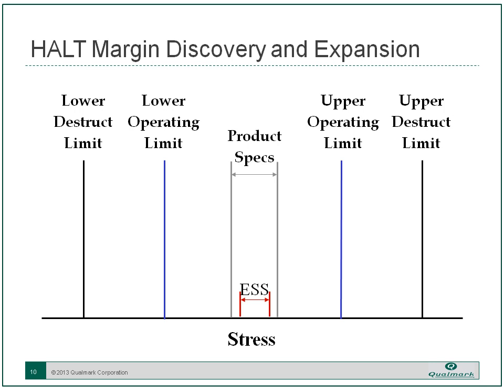Now, you've just got a couple of data points here. You're testing 4 to 6 units when you get into HALT. So you have identified these operating limits. Clearly here we're talking about a thermal stress because we have both upper and lower limits shown here. And we'll have the operating limit, which is a point of soft failure. If you take the stress away, the failure mode goes away. And then we also have the destruct limit, where we actually cause a hard failure. So you identify those points in HALT.